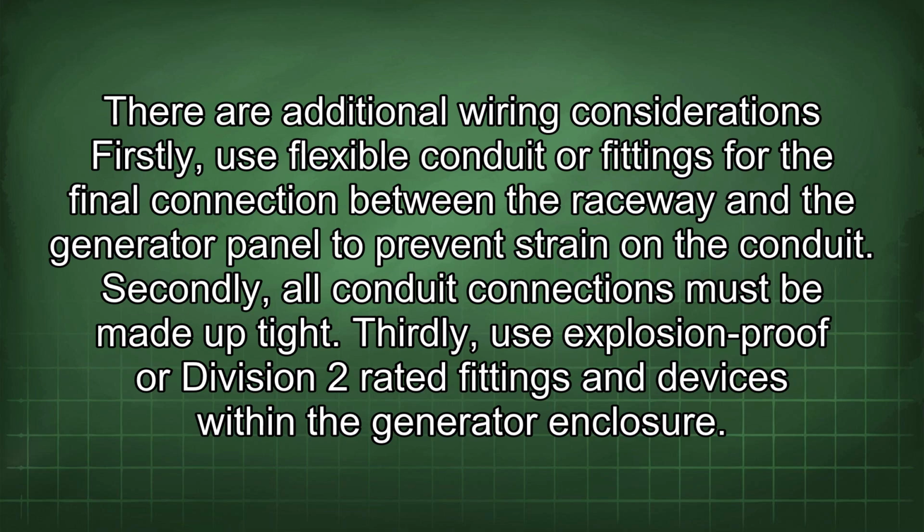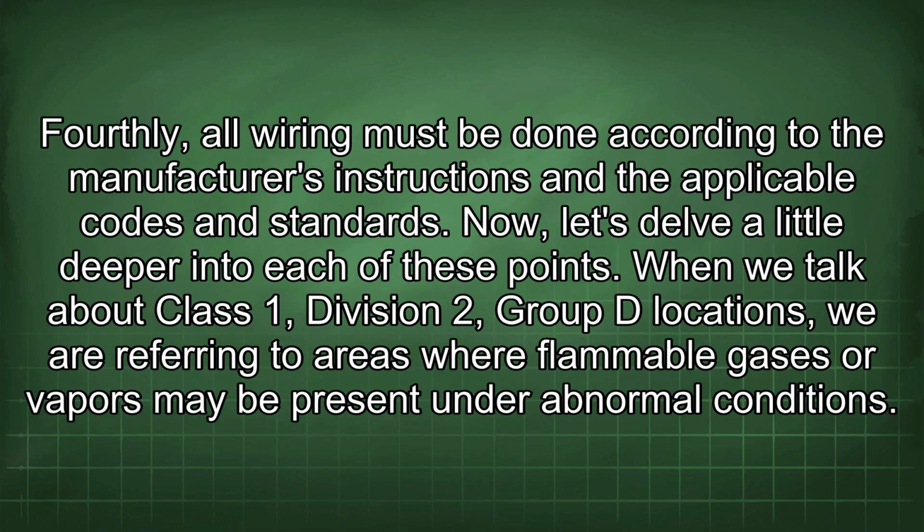Thirdly, use explosion-proof or Division 2 rated fittings and devices within the generator enclosure. Fourthly, all wiring must be done according to the manufacturer's instructions and the applicable codes and standards. Now let's delve a little deeper into each of these points.